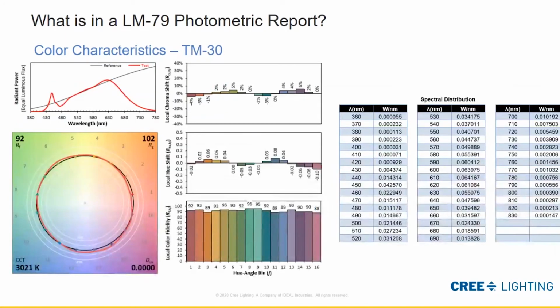And then, going into the next generation of color metrics, we see TM30. TM30 takes that spectral power distribution and puts the reference against it, and you can see that line up in the left-hand corner. We create a better color reference because instead of R1 through R8 samples, we're using 99 color references. So now we're getting a better, broader spectrum and a better comparison across color references.